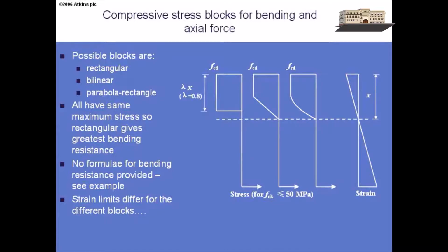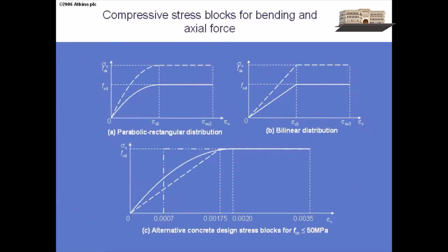Just before I say something quickly about that stress distribution, the other thing is that there are no formulae given for bending in the Eurocodes. There is a formula presented on one of these slides, but it doesn't give you any formulae. So really you are quite dependent on using software or simple formulae that somebody else has given to you. I recommend using the computer, to be honest with you. All this slide shows is the different blocks drawn out.